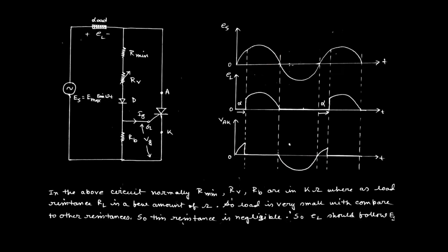As per the normal behavior of the sine wave, when the wave goes after 180 degrees, the polarity changes. It will be positive, it will be negative. Then the anode is negative with respect to the cathode, so the switch is under the reverse biasing condition. At the same time, the current through the thyristor is 0. This is a normal commutation technique. Then the device will be in the off state automatically.